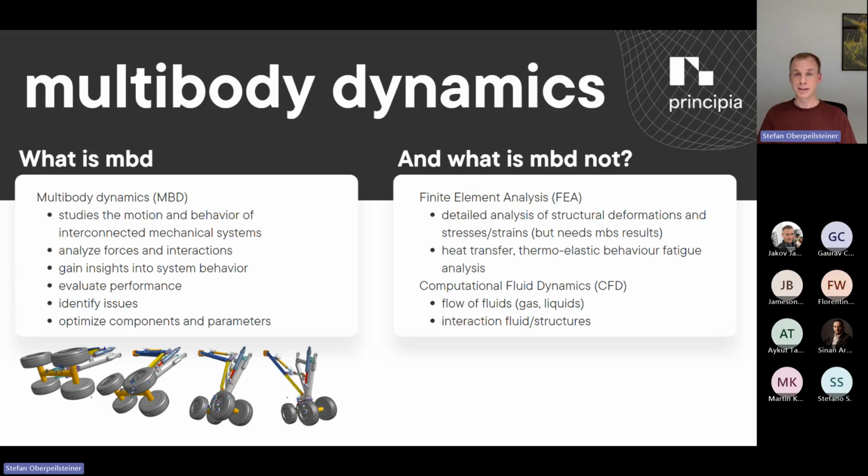So given some time-dependent stresses or some load cases, different load cases in finite elements, you can compute how long your part will survive in the real surrounding. Finite element has one thing to do with multi-body dynamics. Exactly the thing we are talking about today: finite elements often needs loads. When you do not know any load, finite element analysis or finite element models crave for all these details, and you can generate those loads with multi-body dynamic models.